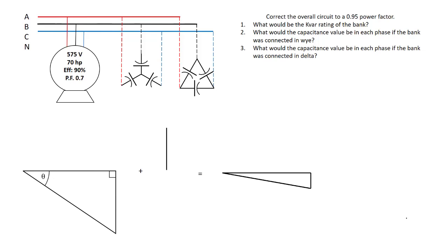So when we're talking about the horsepower motor, that refers to the true power output. So the mechanical, actual physical work. But that is not the power input to the motor. And the power input to the motor is what we have to put on our power triangle. There's other losses within this thing that all happen in order to make this motor operate.